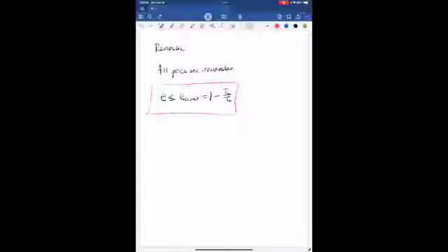So that puts a maximum value on the efficiency of a real heat engine, which as you can see is below 100%. So before this, you might have thought, well, even though the efficiency of a heat engine can't go above 100%, you might have thought you could get to 99% or 99.5%. But Carnot said, no, that's not possible, that the cutoff is actually lower than that. So for example, if the low temperature reservoir was 300 Kelvin and the high temperature reservoir was 600 Kelvin, then the maximum efficiency possible theoretically is only 50%. And that's kind of an amazing thing.